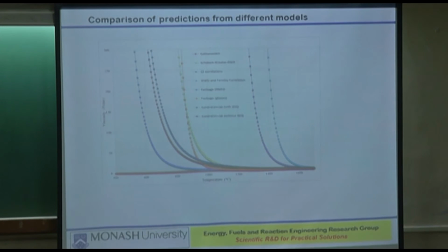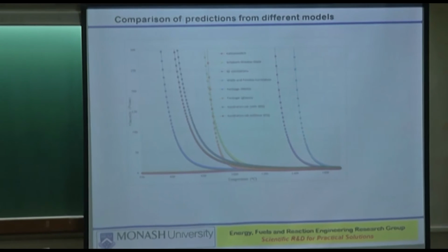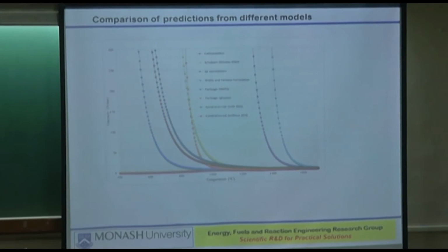and then you need to see the predictions, what it is telling you, because these predictions from the models, the way they are plotted, on the y axis you have the viscosity, and the gasifier manufacturers tell you that we need a slag at a viscosity between 100 and 250 poise, which means 10 to 25 Pascal second, that 25 Pascal second, that is the upper limit.